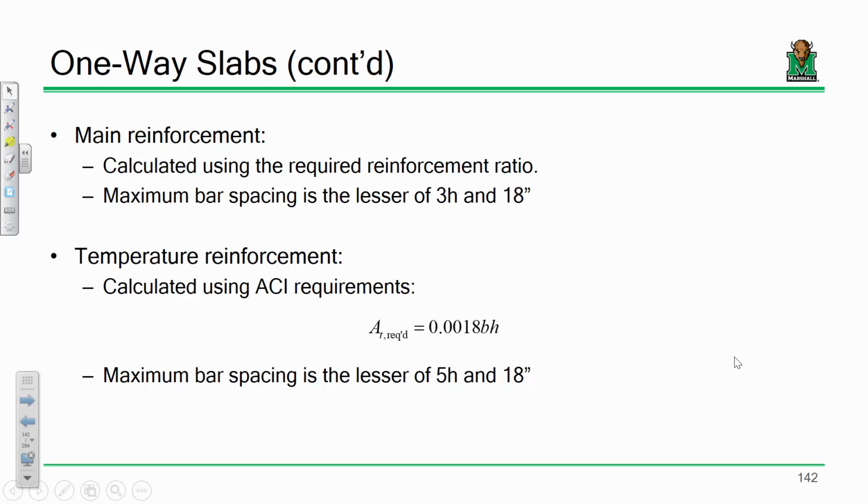In other words, let's keep the numbers simple. You've got rebar that gets bigger as your numbers get higher, right? So you've got number 3 bar, number 4, number 5, number 6. I might be able to do one reinforcement pattern that's like number 3s at 3 inches, or I might be able to do number 10s at 24 inches. In the end it would sort of be the same reinforcement because I've got these bigger bars spaced further and further apart. Now the contractor's probably like, hey, give me the number 10s at 24 inches because that's just less bars on site that I have to handle, right?